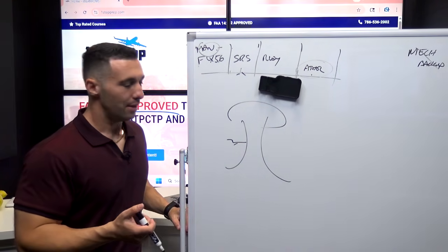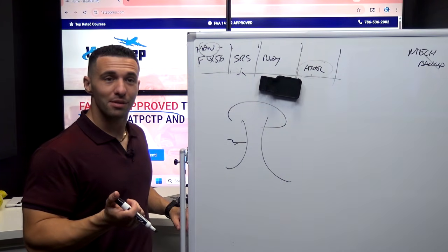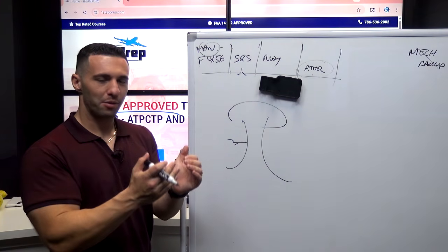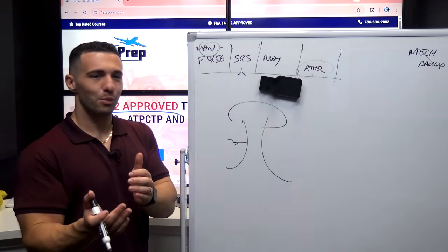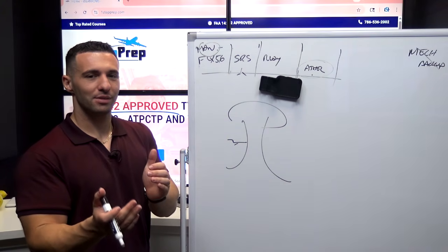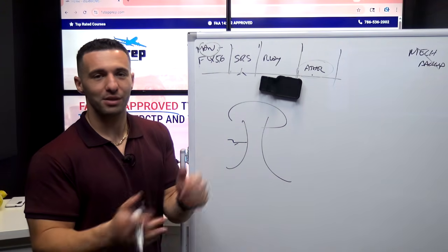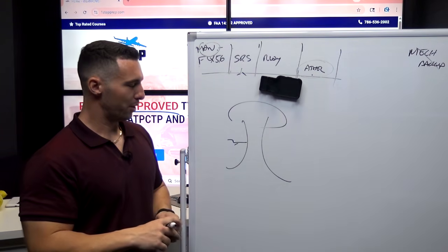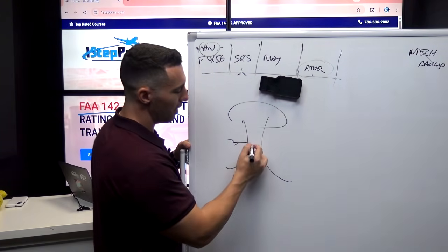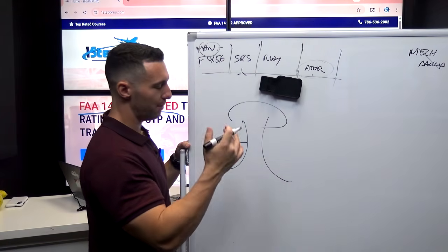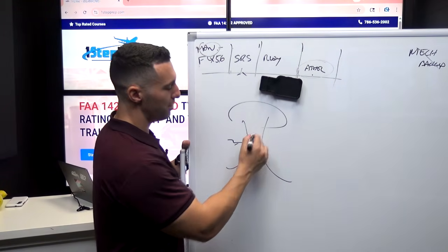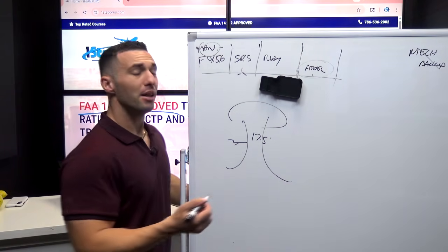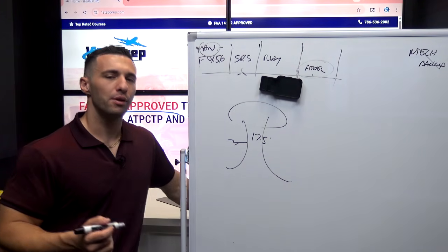It's great. Now, that doesn't mean sit on your hands, because it's very possible that the airspeed decays down to alpha prot, and when it does, one of the things of alpha prot is the autopilot might disconnect, right? So now you're thrown into the fight right away. First you go to the flight director bars, and if they are not there, we go to an initial pitch attitude of 17.5, which is roughly where they'd be waiting for you anyway. And the pilot monitoring, your role is pretty critical here.